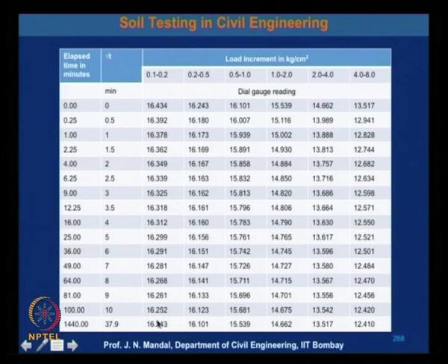Okay. Then again you start from the beginning, let us say next day after the 1440, and you increase the load, that is 0.2 to 0.5 kg per centimeter square, and then you take the reading for the defined time.